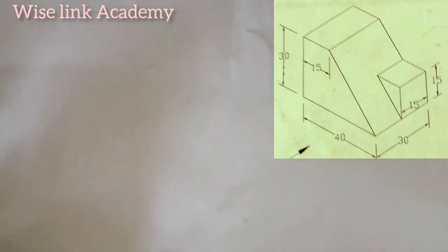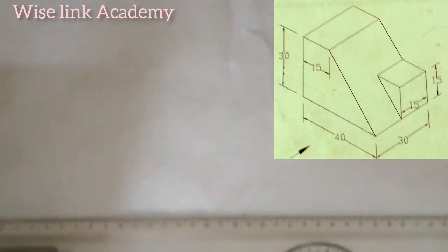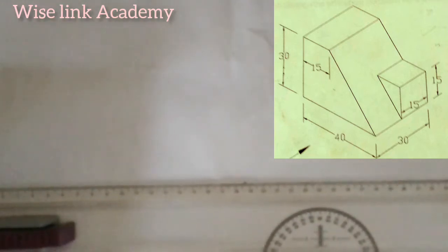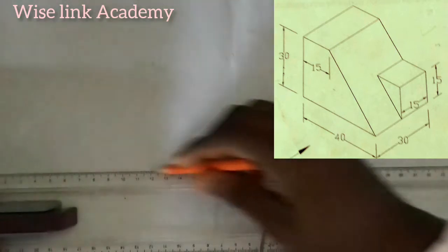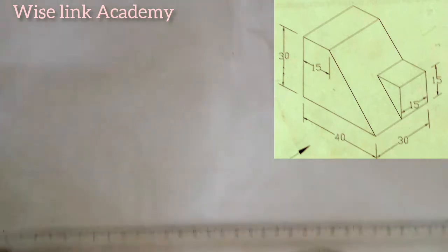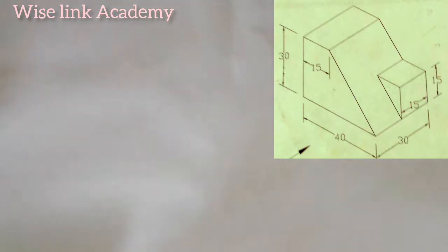Drawing that. For every isometric, as I always say, we need to draw our horizontal line and draw our inclined 30-degree line. So let's do that. This is my T-square this way. I'll take it this way, draw my horizontal line this way, right? This is my horizontal line, as you can see.